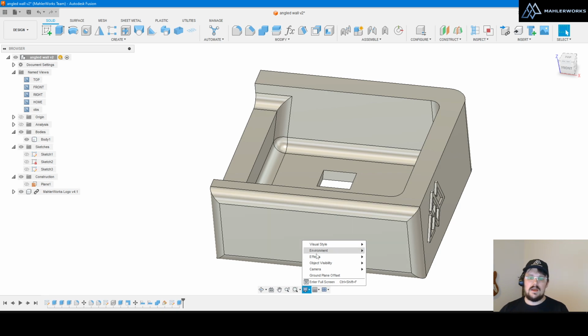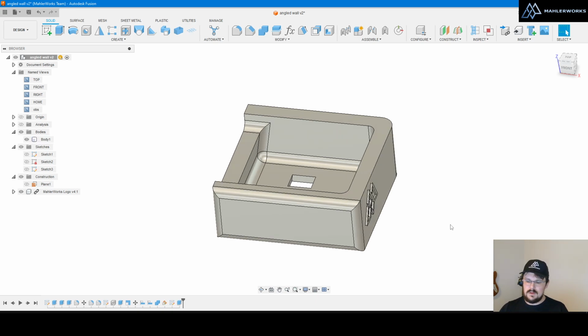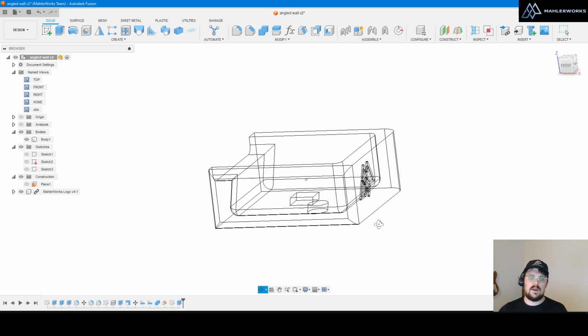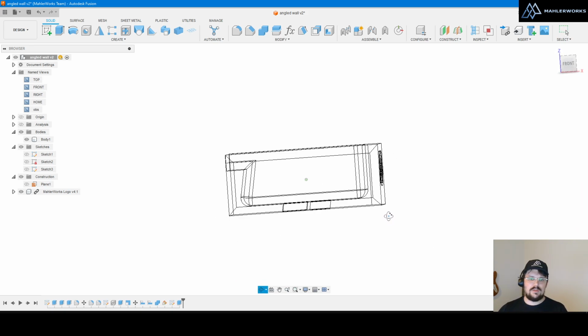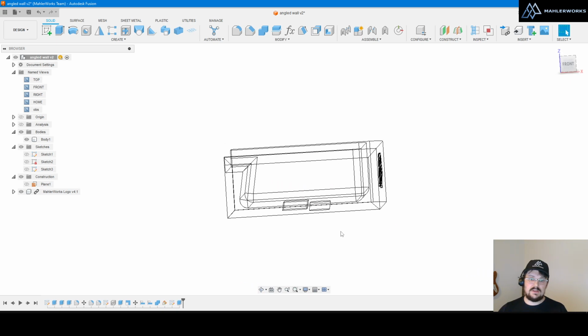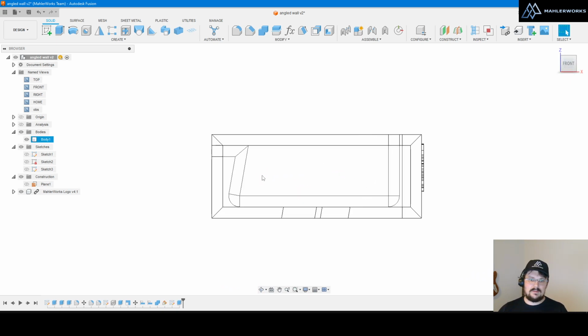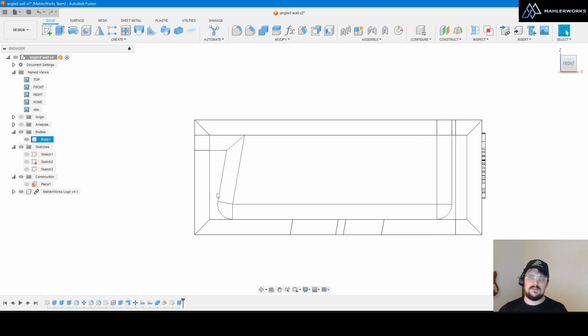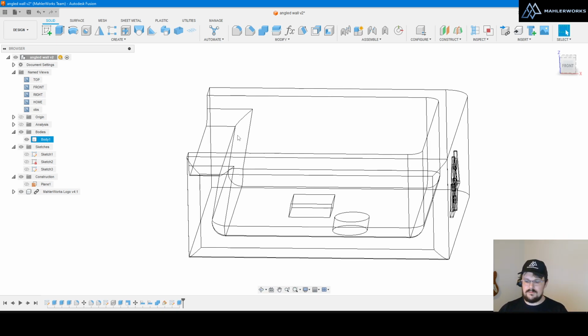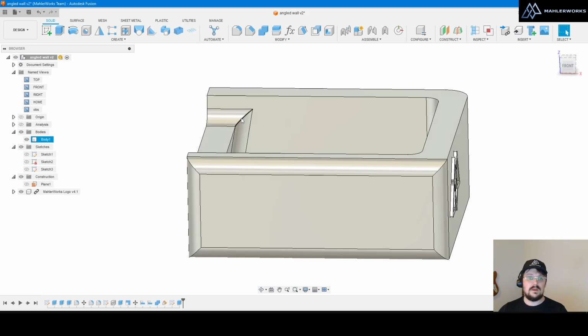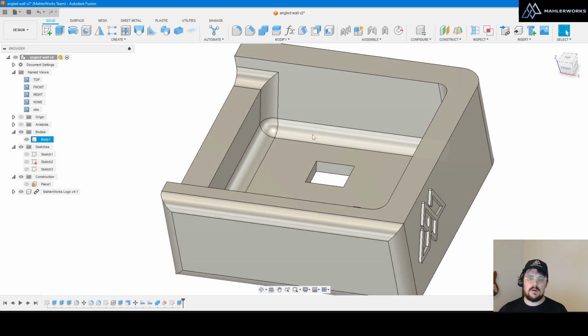Let me show you what that looks like. I don't have to drill into these pages. I can just use the shortcuts, Control plus 6. So I'm on Control 6 right now. I'm going to do Control plus 7, and now I get a wireframe view. I can look through my part, and the advantage here is I can see very clearly that this wall is angled. I can look through my part and then quickly return with Control 6 back to a solid shaded model.